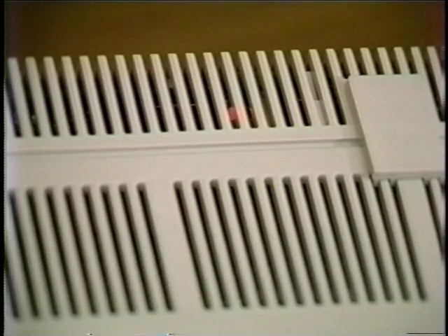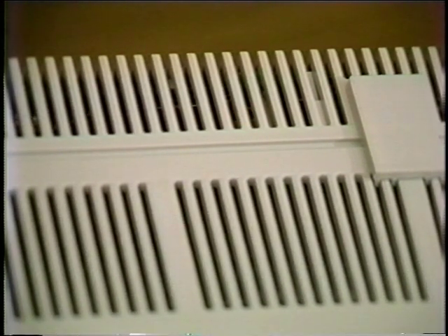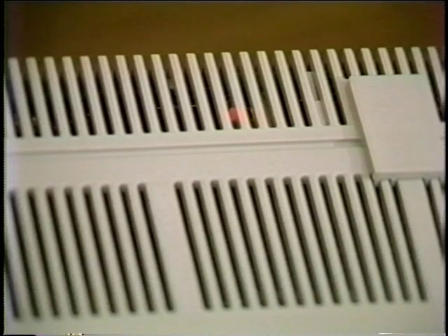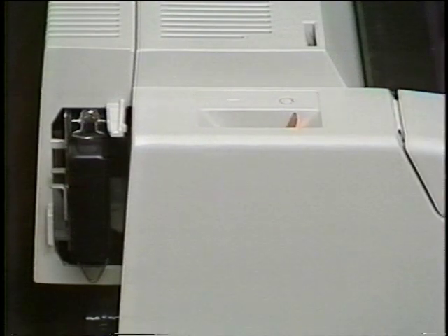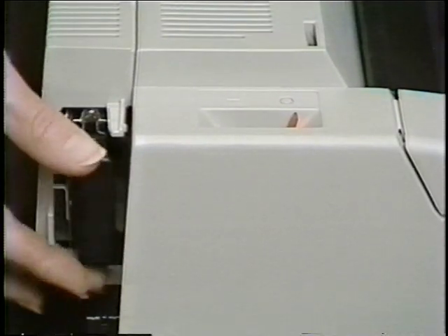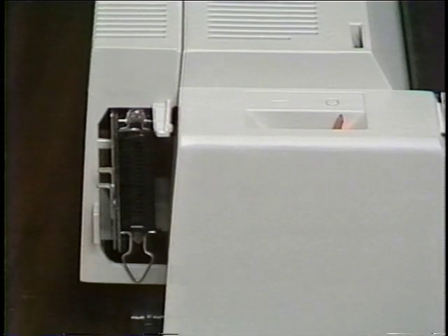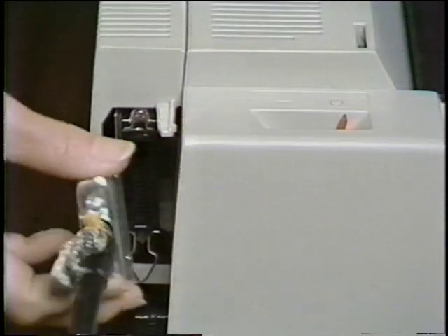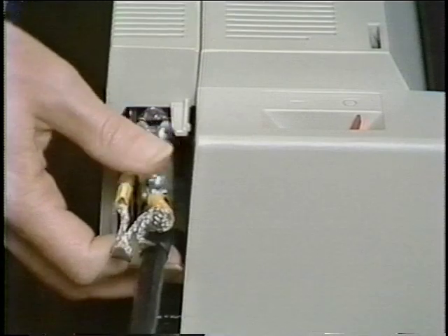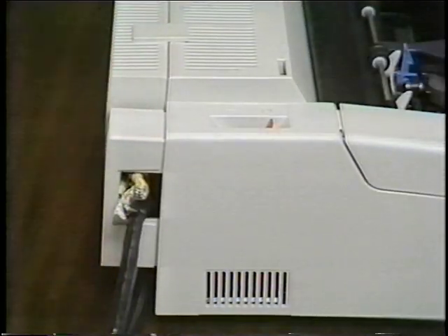Check the printer display board error light. If the light comes on and then goes off, the printer display board is bad. If the light comes on and stays on, the board is good. Set the line feed dip switch to its original position, plug in the printer cable, and install the cable cover. This completes the wrap mode check.